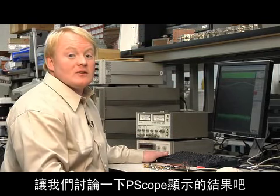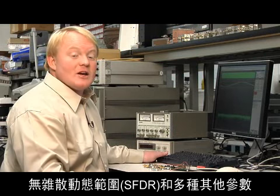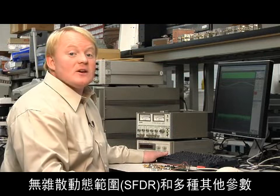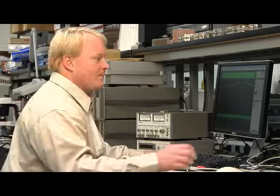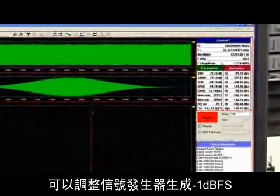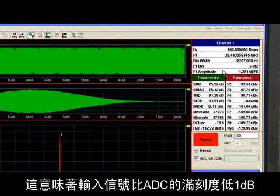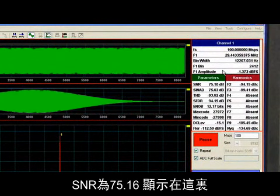PScope calculates the signal-to-noise ratio, spurious-free dynamic range, and several other parameters automatically. These values are displayed here on the side. If you look here at F1 amplitude, you can adjust your signal generator to produce -1 dBFS. This means that the input signal is 1 dB below the full-scale range of the ADC.